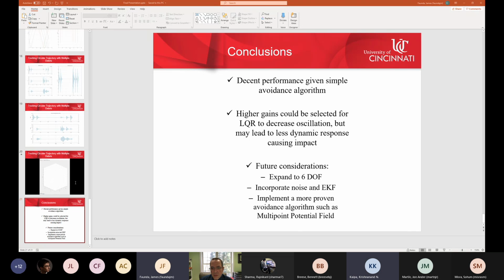Then it finds if it intersects, and if it's within a certain tolerance range, it goes into a while loop and increases the orbital altitude of the trajectory. That way it's pushing the orbit out until it misses the debris within the tolerance. Then it returns this new trajectory until it is past the impact time, or the debris is out of distance.